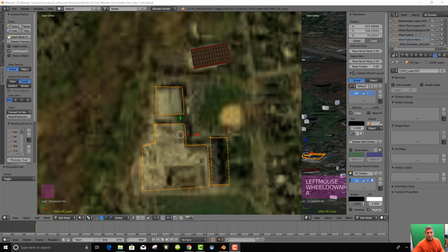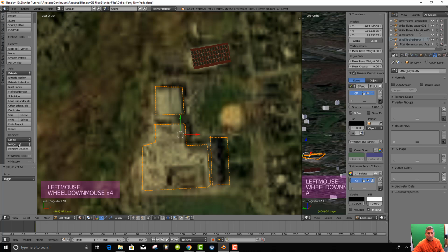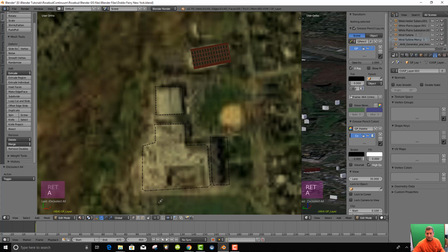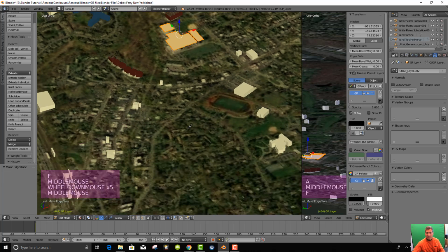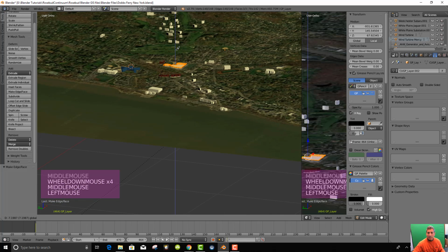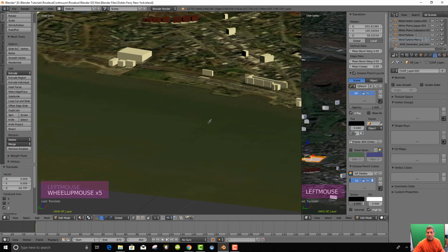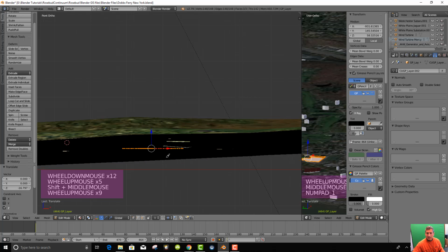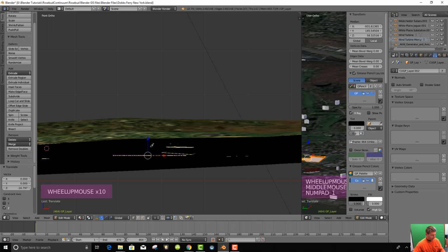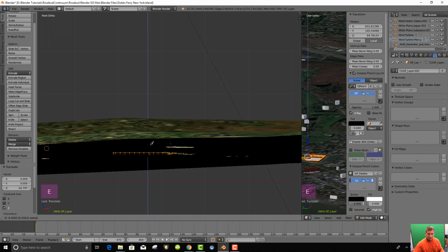Once again, go to Tools and remove doubles and see how much double removal works for you, and then hit enter. Now we have the ability to select all of it and put in faces, and now take those faces, bring it down onto the landscape for the high school, turn this around like this, and try to get some kind of height by doing E for extrude.